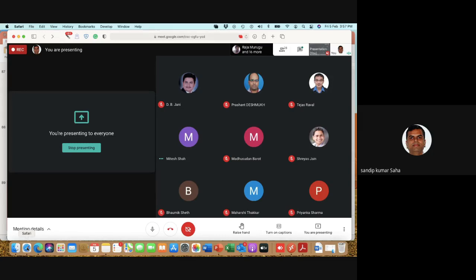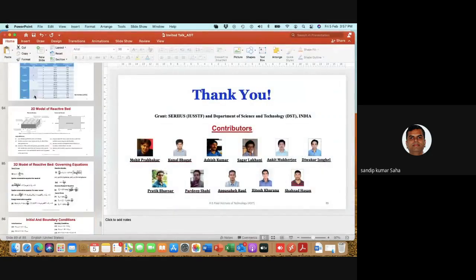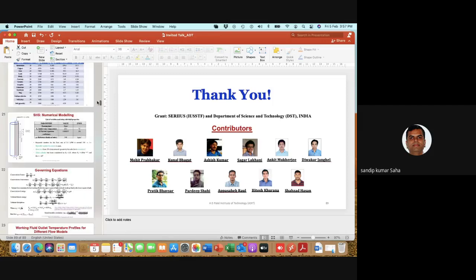So that we use before the turbine. But the problem with the solar drum is that you will get saturated liquid at the outlet. Although pressure is high, saturated liquid you will get, saturated vapor you will get. Now, if you get saturated vapor, the turbine blade will corrode. So that's why you need an extra heating arrangement before the turbine. Those problems will come. I believe I have mentioned this thing. Maybe I didn't. Just 1 minute.